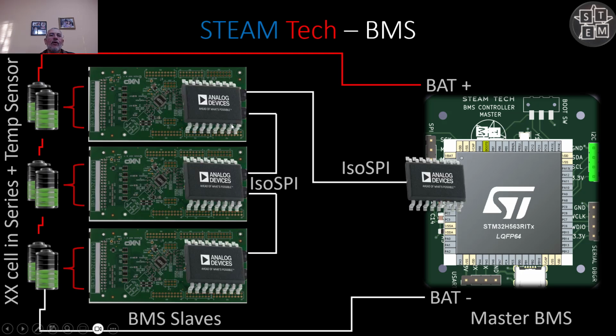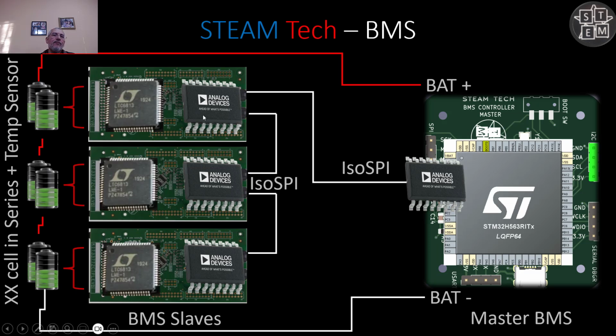I also chose from Analog Devices this LTC6820 chip, which will convert the SPI format, this is a transceiver, to an isoSPI. This connection here is nothing but a twisted pair. So only two wires are connecting, either from the slave BMS back to the master BMS, or between these slaves we're also using a twisted pair.